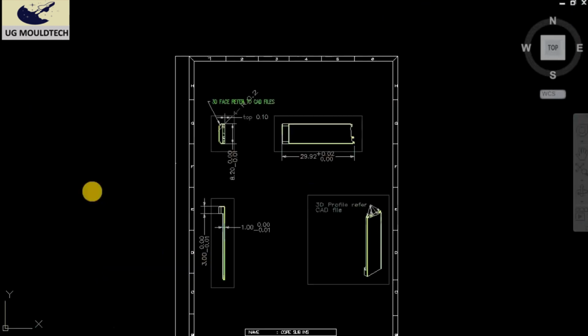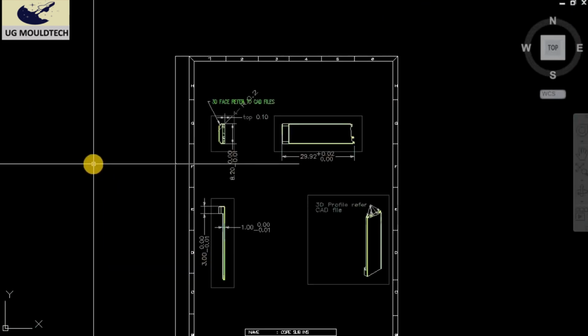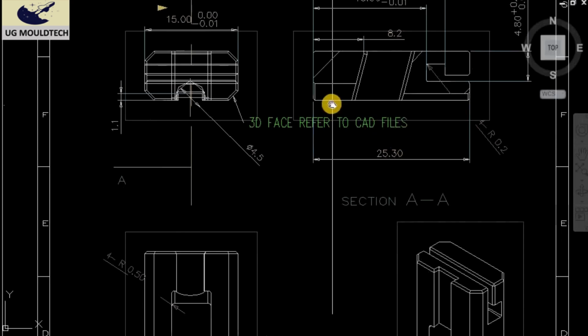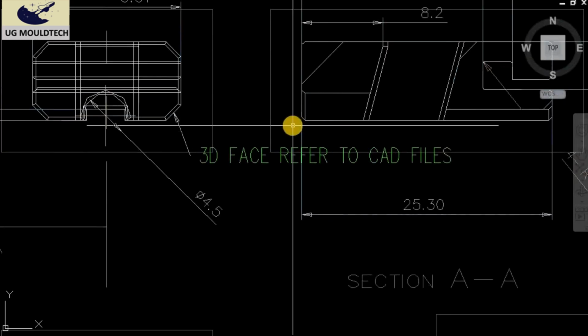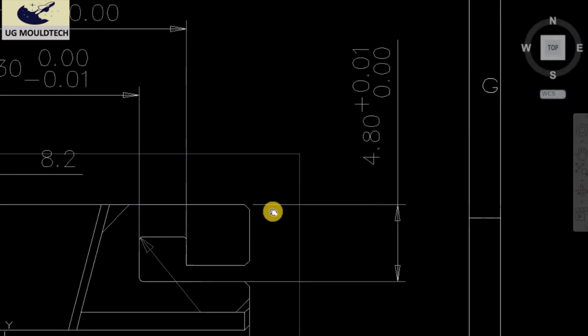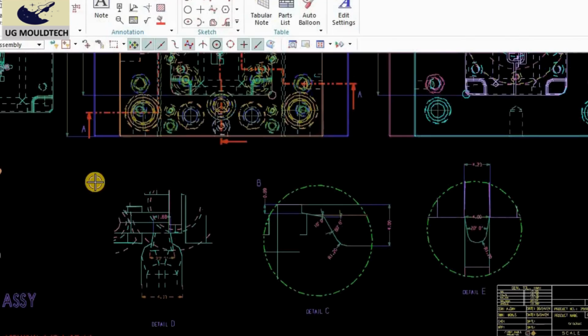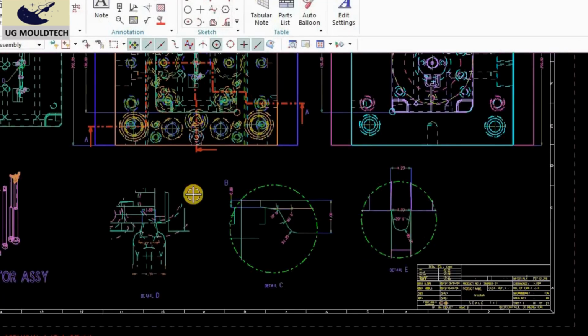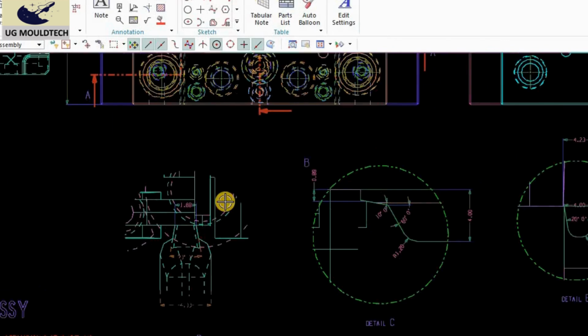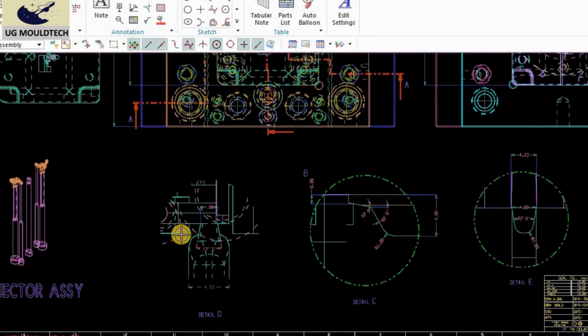You must check all the control features that are being given in the drawing. Okay, friend, we must check all the critical dimension features in cavity, core depth, ejector pins, okay, friends, cooling channels, because these need very precise dimensions. It may be flatness or squareness. Friend, we must check that GD&T is applied where our precision is needed, such as flatness, positioning, or concentricity.